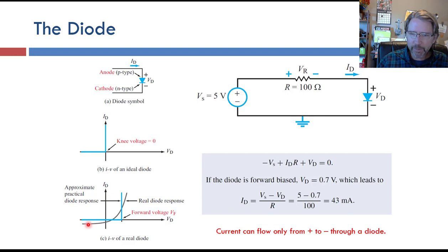An actual diode has an exponential, so this is the real diode response. And you'll actually do a circuits lab where you measure this. You'll measure current and voltage across the diode, and you should get this exponent, and you'll find the coefficients of the exponential to match so that theory matches experiment. That's the way it really works.